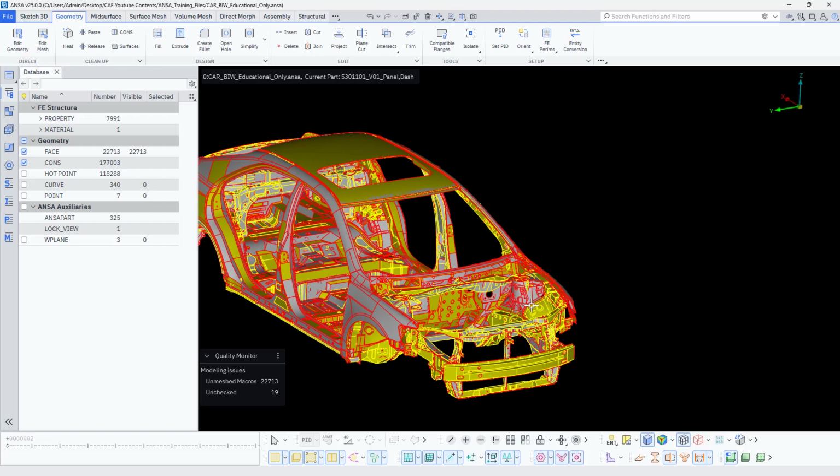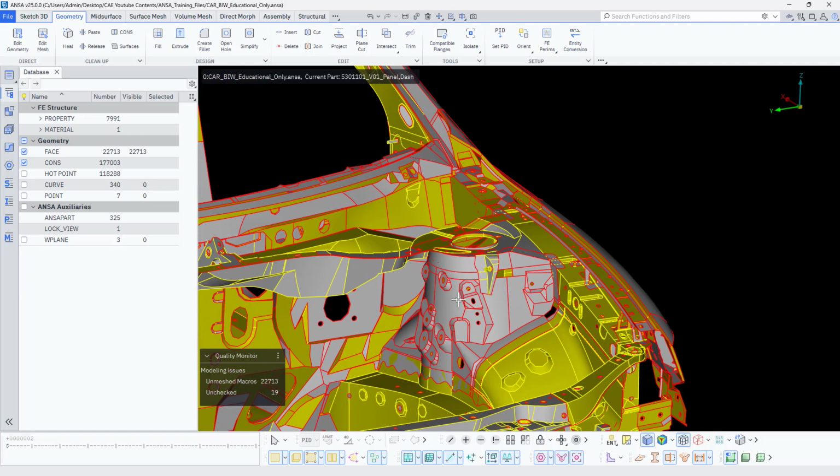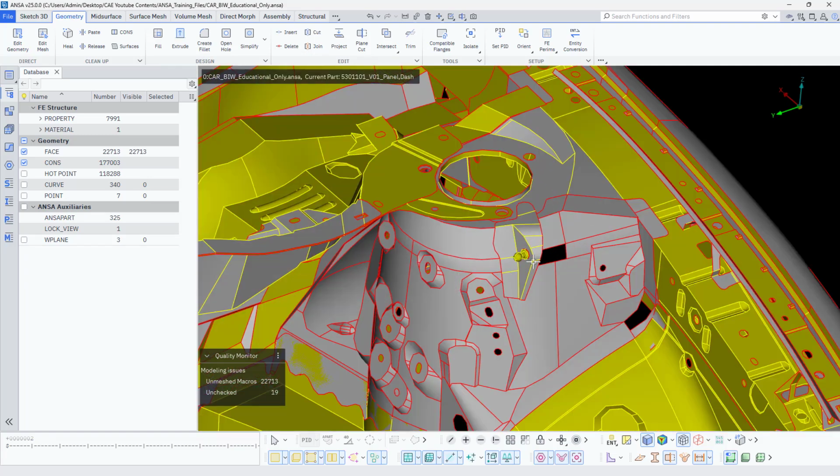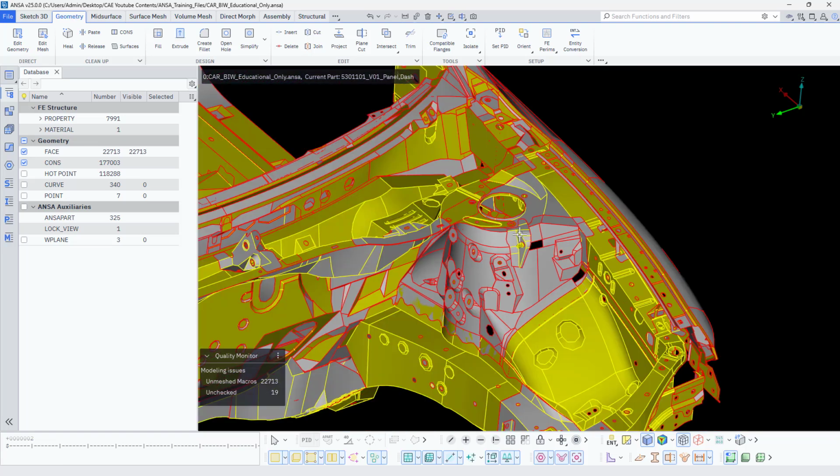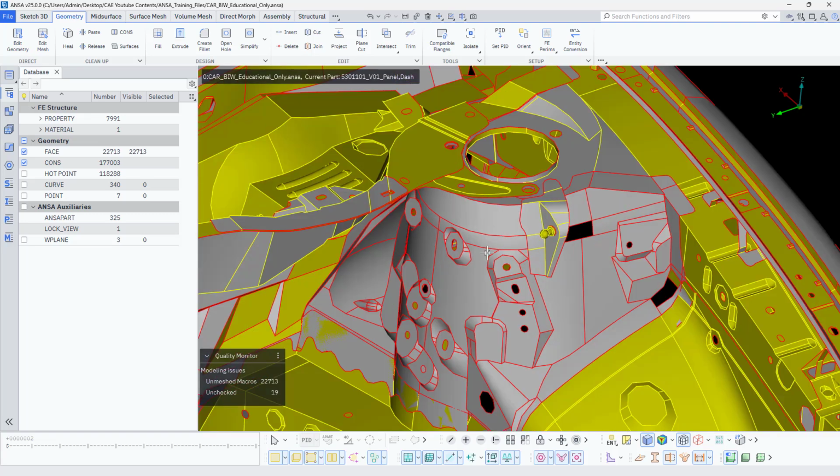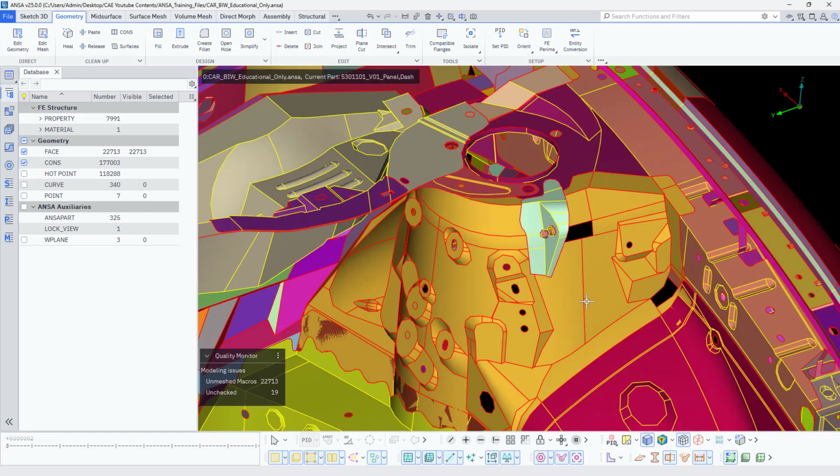Well, let's jump into the modeling activities now. I would like to work on this particular component that we call the front dome. If you take the car, it is the front left dome, we can call it. Okay, how do we isolate this? I'd like to switch from entity mode to PID mode, and this is a single PID.